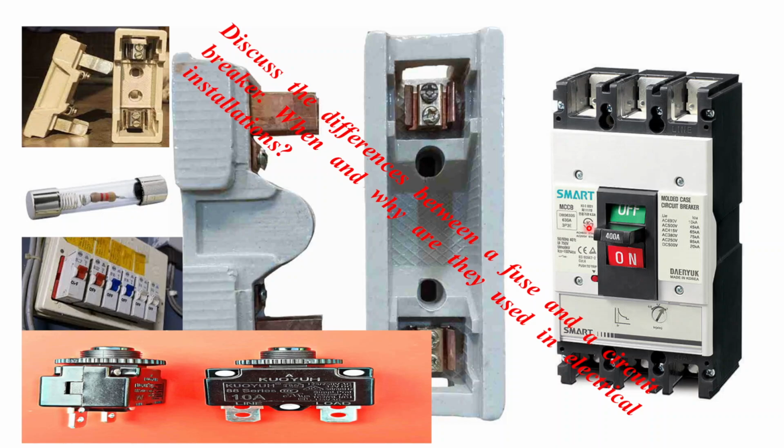They offer more flexibility and control compared to fuses, as they can be manually operated and can also include features such as adjustable trip settings, remote control, and indication of the fault condition. Circuit breakers are available in various types, including thermal magnetic, magnetic only, and electronic trip circuit breakers, each offering different characteristics and capabilities.